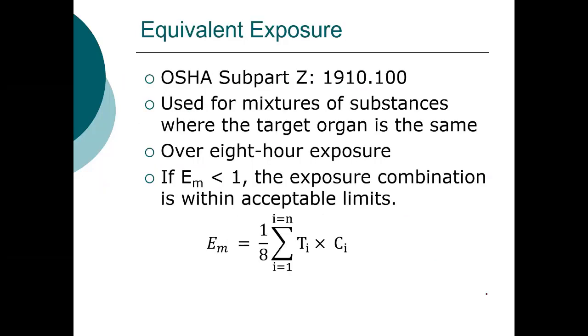We also talk about equivalent exposures. So here, these are set for mixtures of substances where the target organ is the same. That's critical. Looking at exposure over an 8-hour period, if the equivalent exposure is less than 1 for the aggregate of exposures, then the combination is within limits. And we'll do an example problem, which should help.